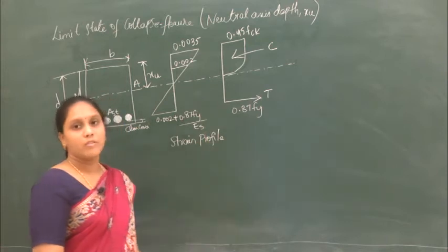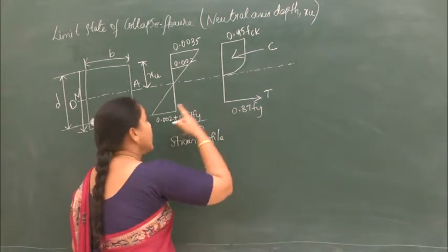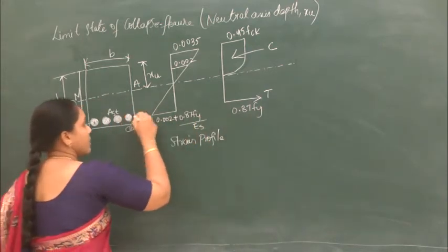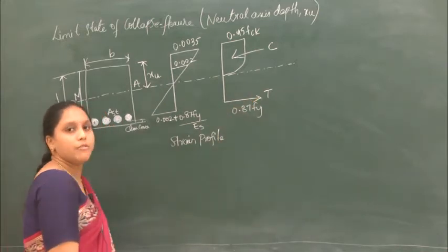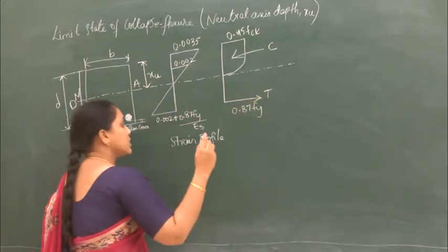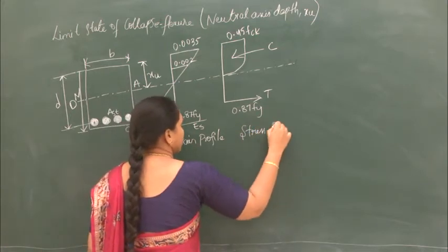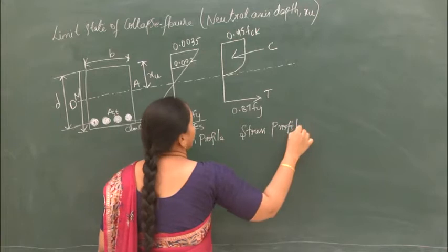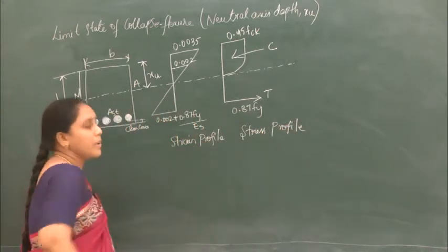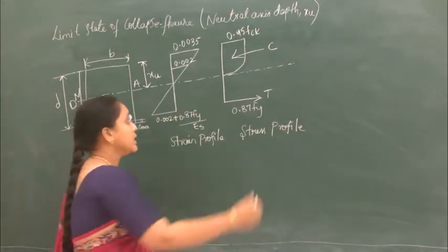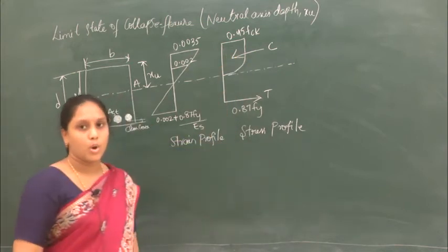So here we have the compressive forces, and here at the tensile steel we have the tensile forces. So this is going to be our stress profile, and this is our stress block.